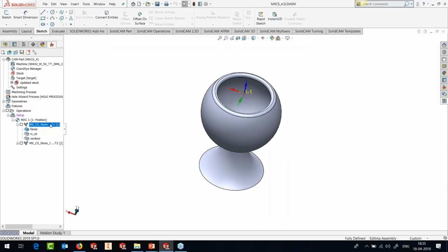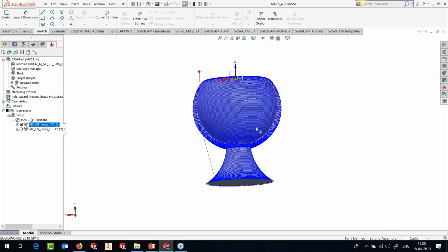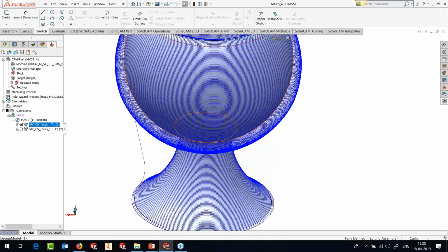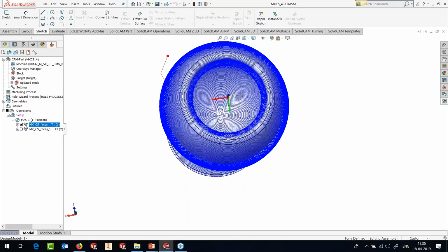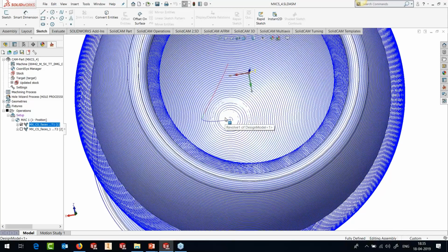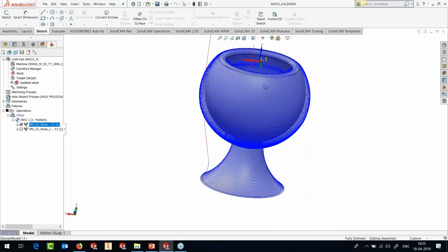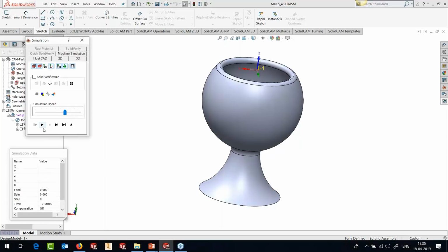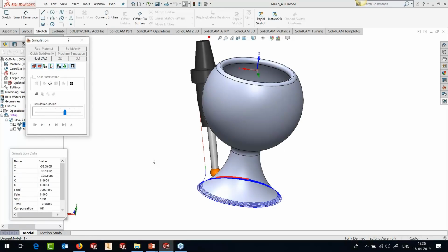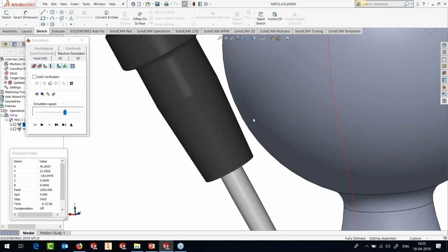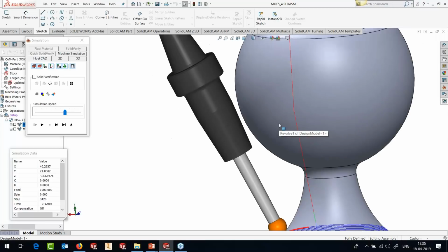So this is how the tool path looks like now. Single tool path, right from start all the way till the end inside. You can start applying your brains and now start looking where all you can use this kind of an application. So if you look at the simulation, this is how it will simulate the tool path. Absolutely no collisions. Wherever you stop, it's exactly leaving the space between the holder and the part.